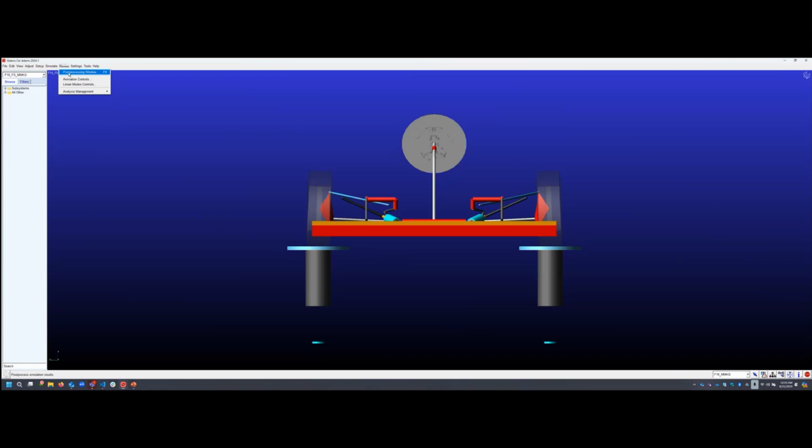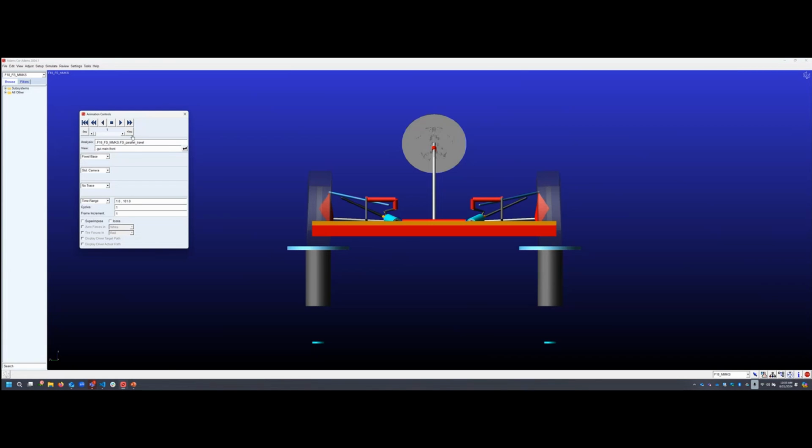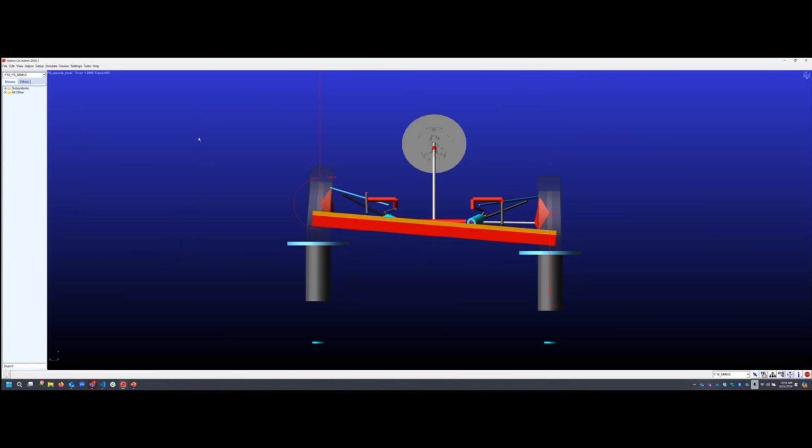And the other thing is how it works in roll. So we wanted two things, not just for it to sync with the tires, but we also wanted decent performance in parallel wheel, as in bump, and also roll, since most of the time the car is rolling in terms of how it travels around the track. So as you can see, again, the same thing happens. It rolls with the suspension. And the main advantage that we get actually is the same.